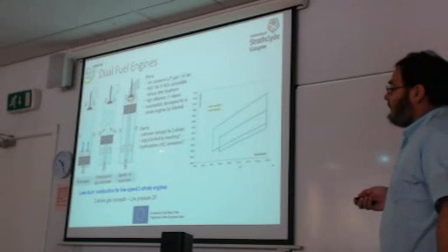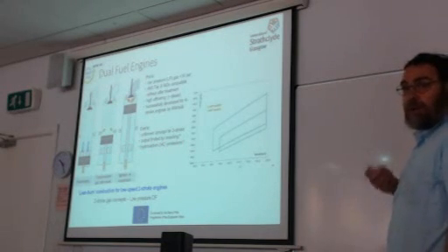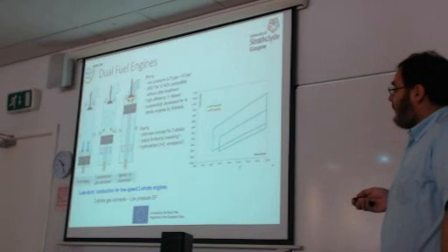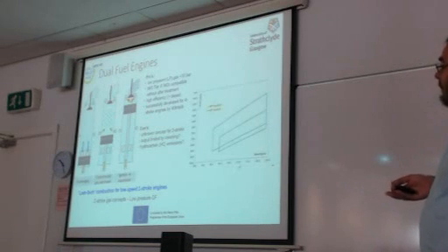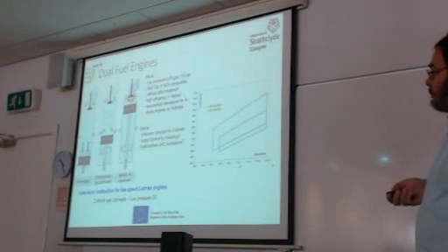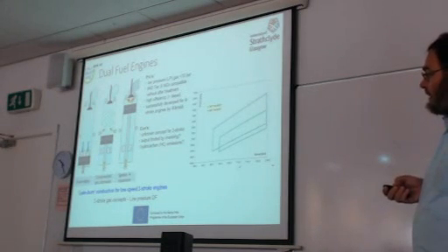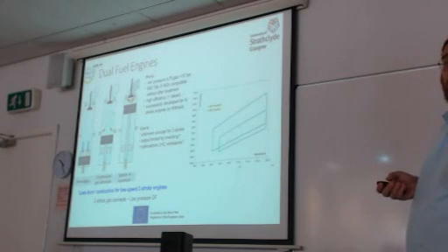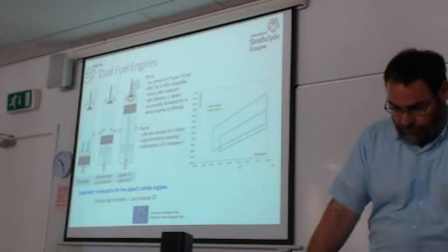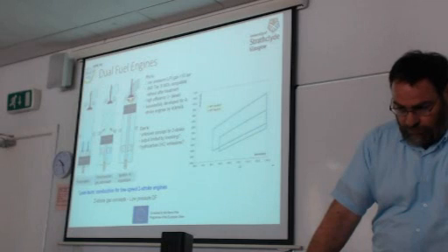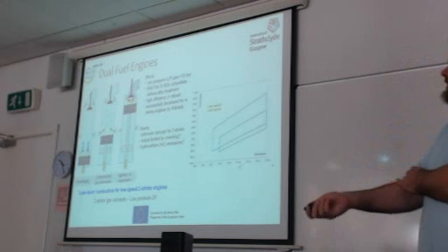The engine is prone to knocking, so a lambda operating window is also required. Lambda should be around 2, as we discussed earlier. And of course, there is an issue, or should be an issue, with hydrocarbon emissions due to the lower pressure level. But the fact is that Wärtsilä released this concept, released these two-stroke engine models, and this engine also exists in the market.